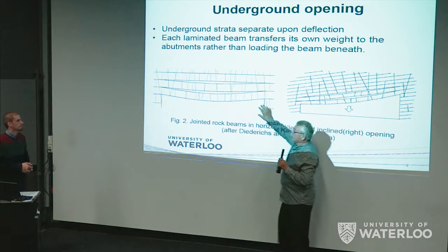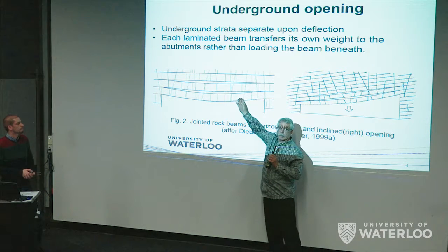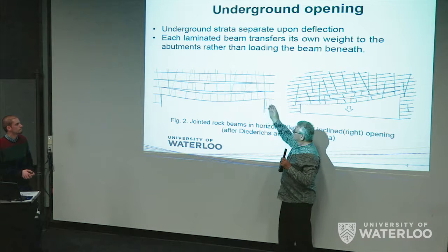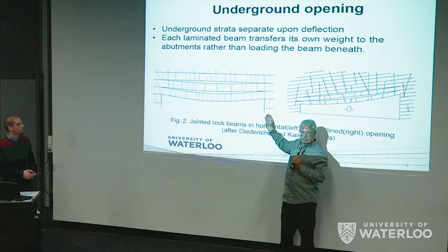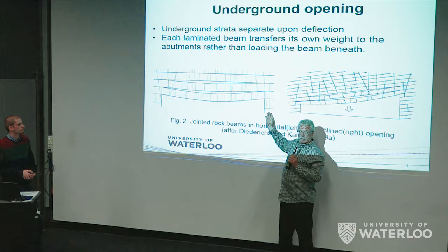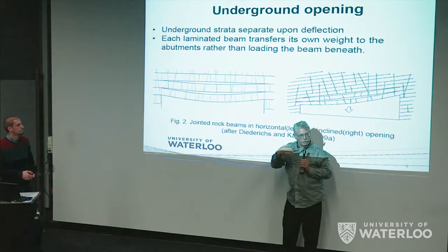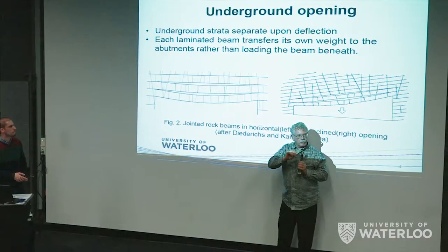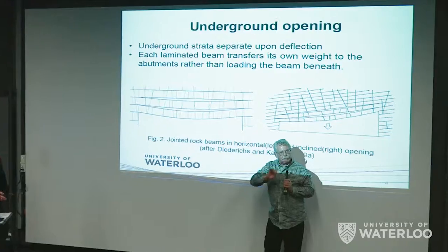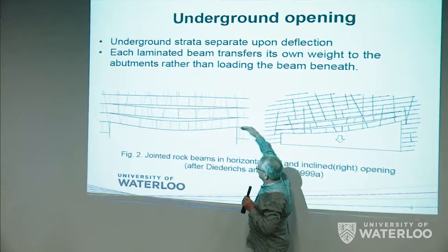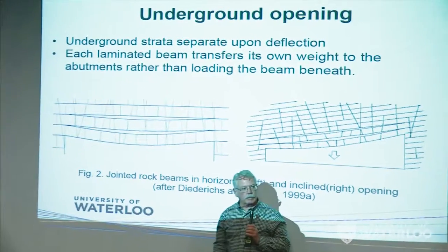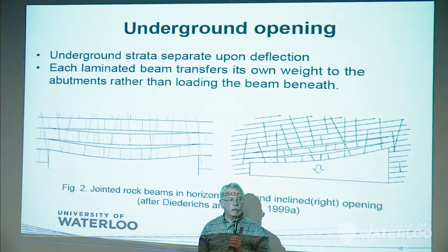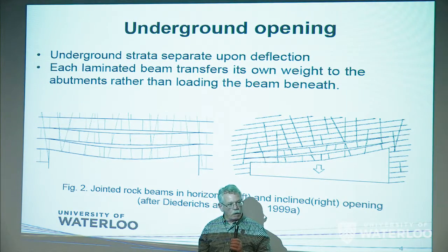In a cavern, in a very simple model, you might look upon this as the elastic rock, and the salt rock is here in the abutments, okay? And this material, depending upon your pressure limits and your depth and your temperature, is behaving viscoelastically or elastoplastically. I mean, elastoviscously. It's moving, it's creeping. So this interface turns out to be an important interface of slip. That requires a composite material model.